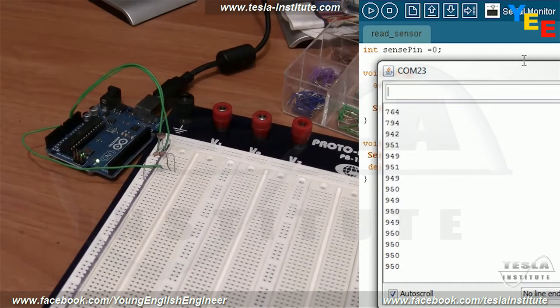Why is that? Well, it's partially because of the resistors that we've chosen and the inherent fact that you're going to lose some values by using a voltage divider, which is fine. We don't need the full 1024 of resolution. You can overcome this by setting up an op-amp and doing a few other things, but it's not really that important to us. If we want, we can try to change the resistor to a 1K resistor and see how that changes it.